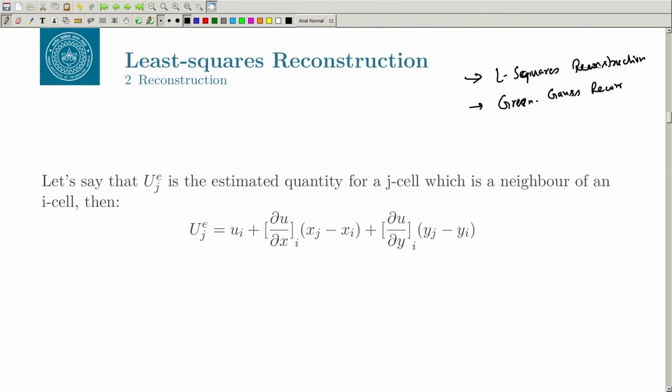You can see whether in OpenFOAM or in Fluent, you will have both these approaches. In fact, in Green-Gauss, you would see there are two approaches: one is cell based and the other is node based. This is there in both Fluent as well as OpenFOAM. Most of the software that you use will have options for you to choose among these three. There is another approach called pseudo Laplacian, but we will not be discussing that today.